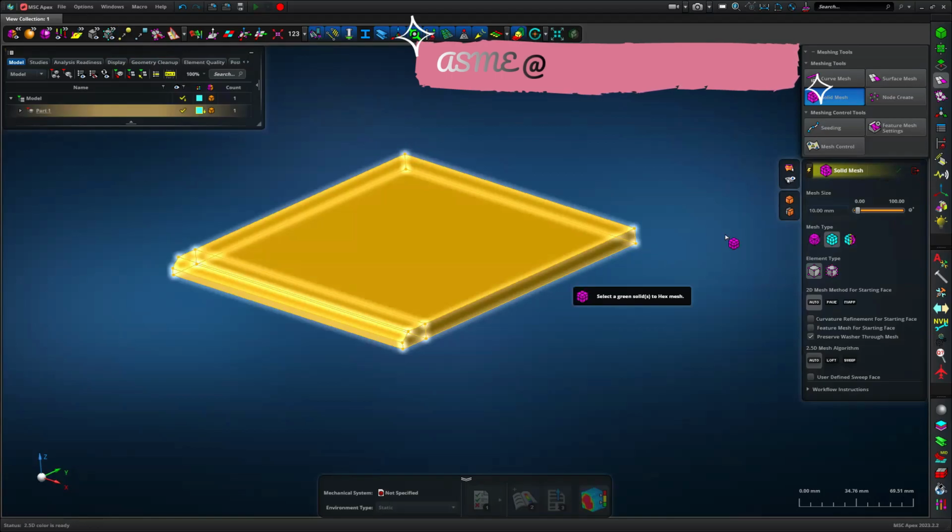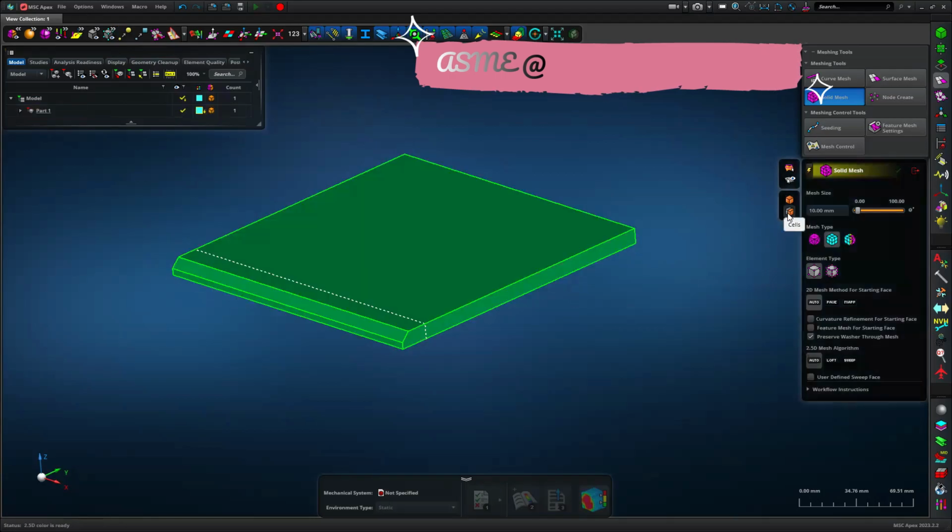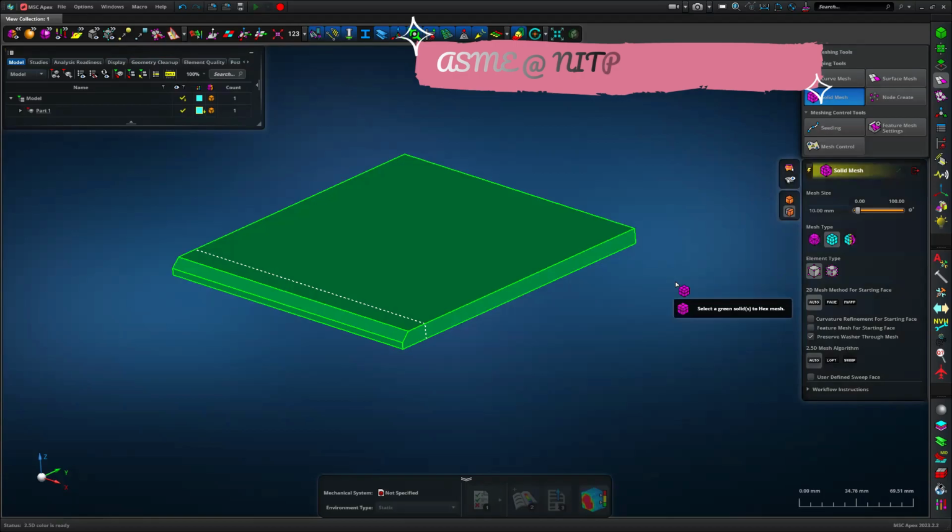For that, there will be an icon here below the solid, that cube. There will be something called cells. Just below that cube icon, there is one more partitioned cube. Cells. Click on that cells. The element type is this one, that 2.5 hexa. Element type linear only, default.